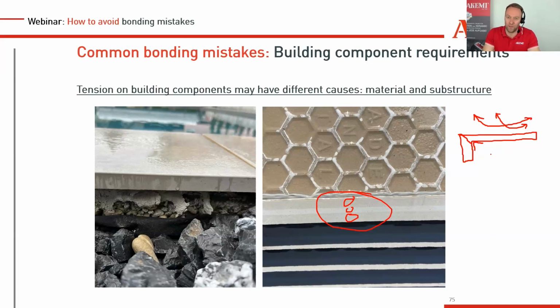If you're sure that it does it, maybe you have seen it already, or you have it outside, especially when they are bigger, like when they come to 1 meter, 1.20 meters in length, and when they start moving, and you're sure your material is doing it, then I will not take the risk. Use directly here a flexible glue like our Akemi elastic, for example.